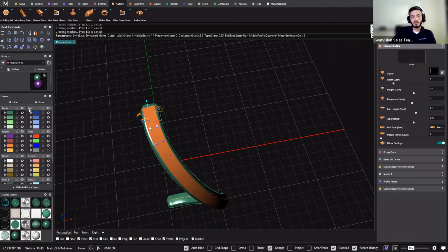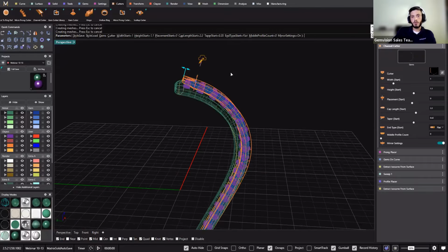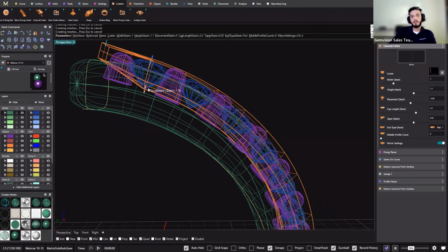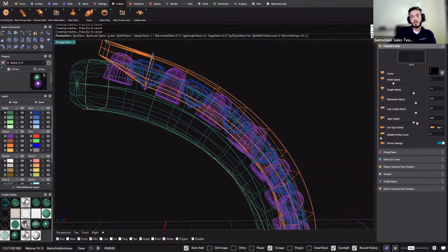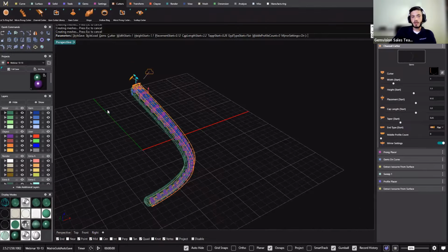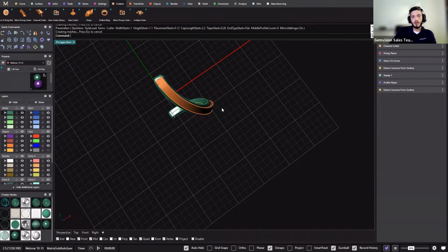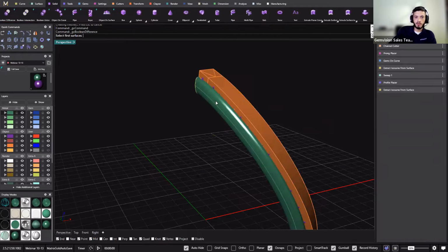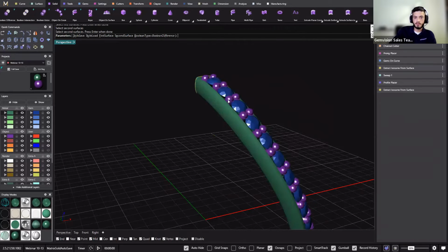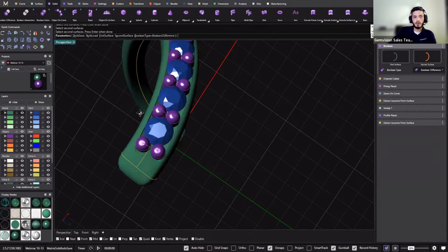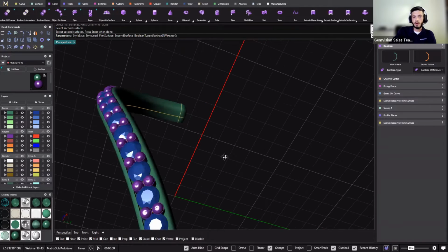Let's make sure he's not too deep, so I can go to wireframe. It's a little deep, so let's pick up. Then let's come back down with our taper. All right, so now I can right click. And the last thing we need to do is a Boolean. So I'll Boolean difference. And there we go. Okay, so I can right click now.